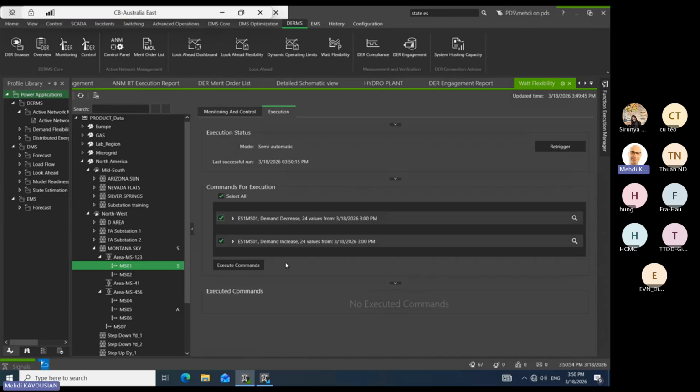One thing that we need to be clear on: for the array signal, the schedule is available only for the DR which supports the protocol IEEE 2030.5. Currently, the schedule is like that. So basically, we need to be clear because of this project, we might not have the DR under protocol 2030.5, so the schedule command might not be available to your DR at this moment.